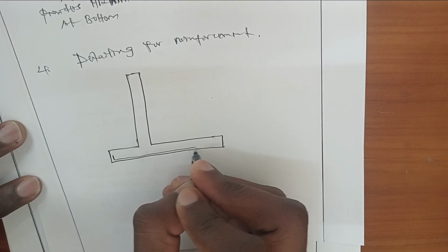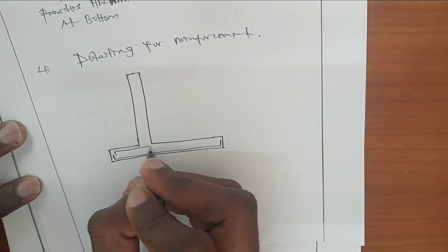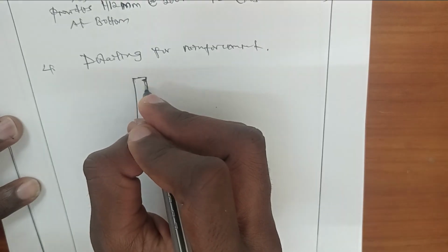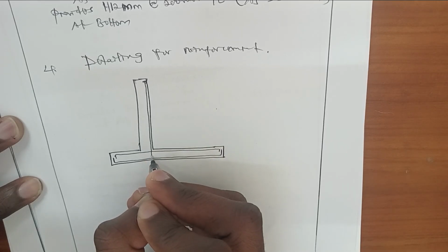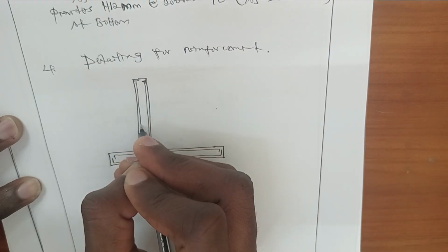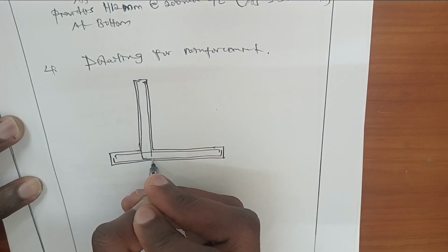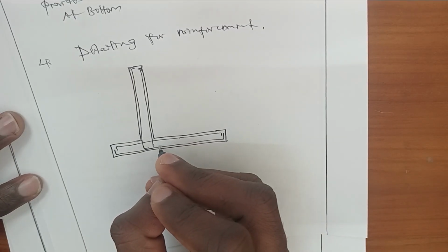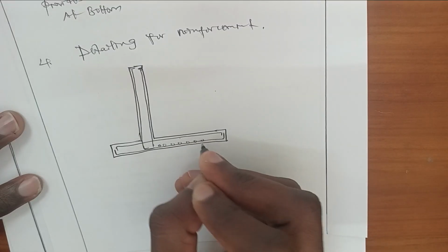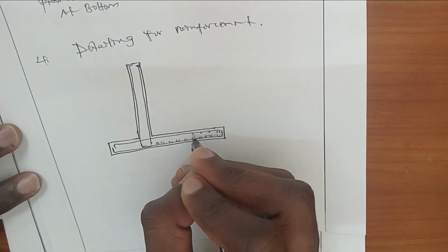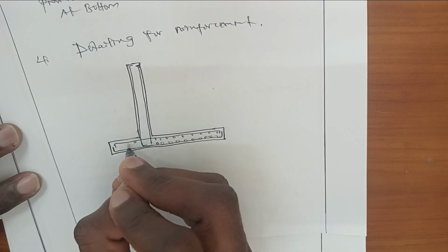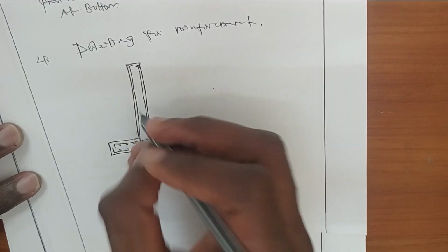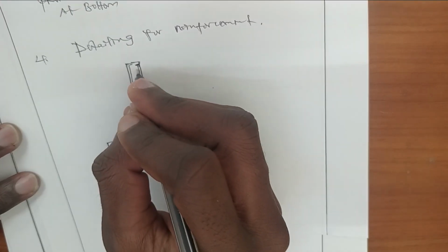This is mesh reinforcement. So to prevent shrinkage and cracking, as well as for the stem, it will be in this way. Inside the mesh reinforcement, there will be a number of bars located in this way, with a spacing of 200 millimeter, one bar after another.